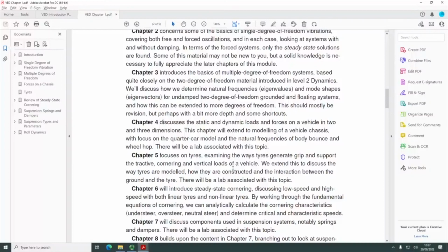We'll talk about how tyres generate grip and different theory around modelling. Often tyre modelling is based upon empirical evidence, so they test the tyre, and then you can build a model based around the test results, as opposed to developing it from first principles. Because of the way tyres interact with the road surfaces, there's all sorts of variables at play that make a difference.